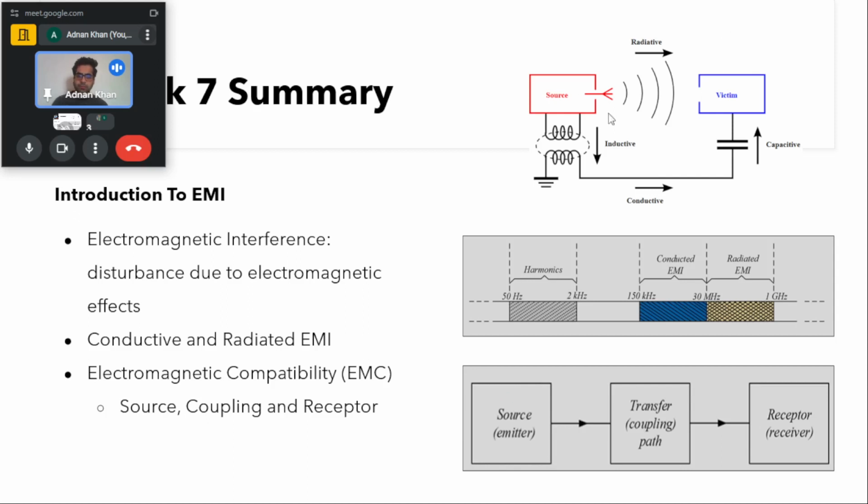The other thing is, we have a source where this EMI is getting generated. As we know, this EMI is generated at very high frequencies, in the range of higher hundreds of kilohertz and so on. This source can then act as an antenna, which can radiate this. This radiation is very ineffective, but it can certainly affect the operation of other devices.